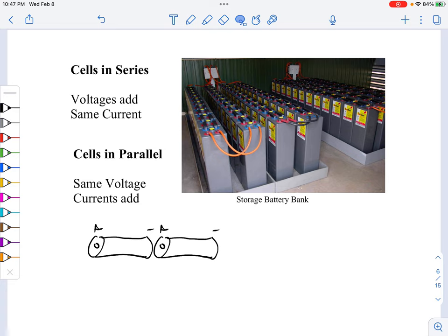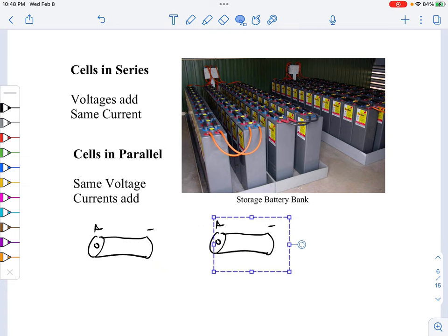Why are you doing that? Well, because you're putting the cells, the batteries, in series. Why? So that you get a higher voltage. Because sometimes the voltage requirement of your light bulb is higher than the 1.5 volts that you typically get in a battery you buy in a store, like a AA. So that's one way you can connect it. Careful, a lot of times if you've changed batteries, inside the battery pack it will look like the cells are in parallel.